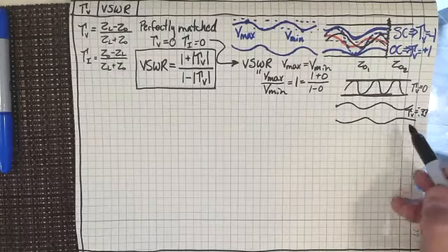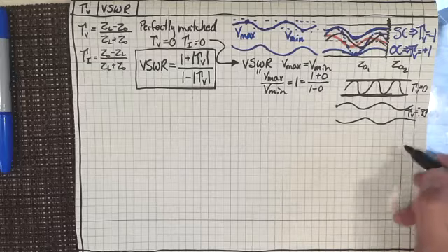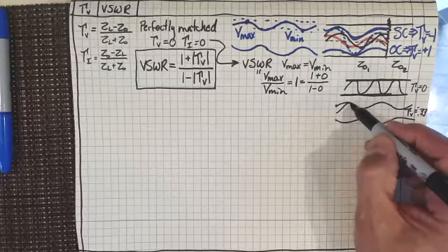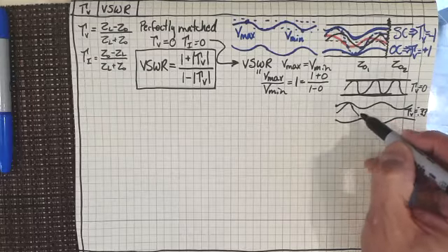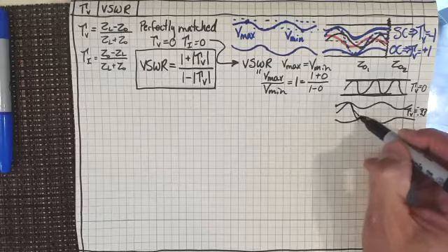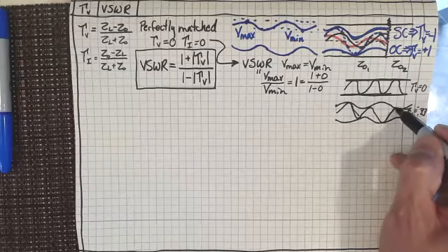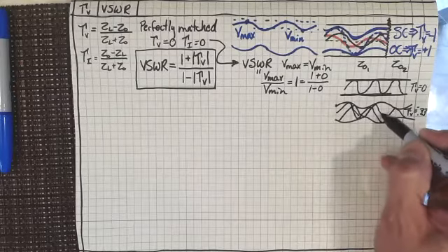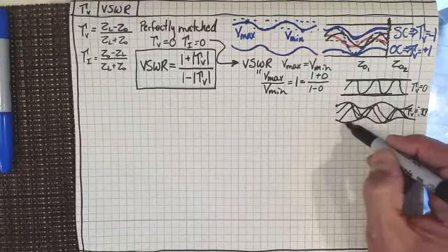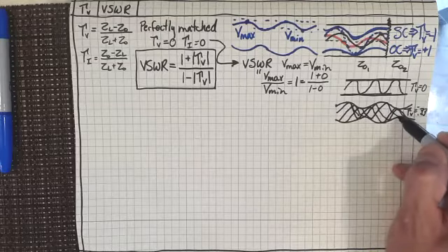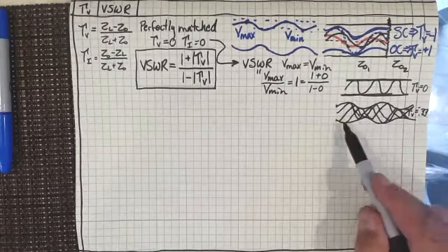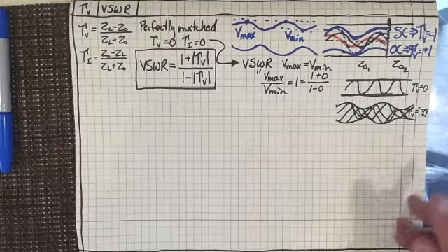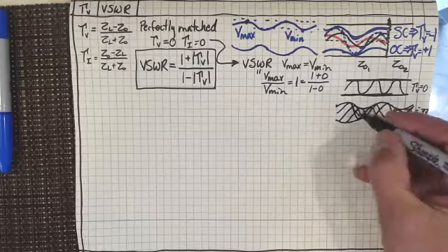Okay, now if I was going to take this a step further, right? And so now I've got the same thing. And of course, inside here, what's really going on? We've got waves that are coming down. Oh, I drew that one wrong, like this. And we've got other waves, because sometimes what's happening is they're not adding together exactly. So this is what I get. So if I have a reflection coefficient of about minus 0.33, I'd have my envelope that looked like this.